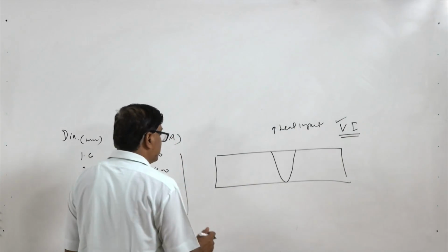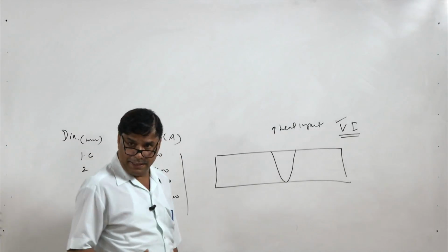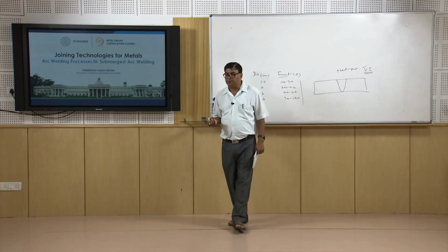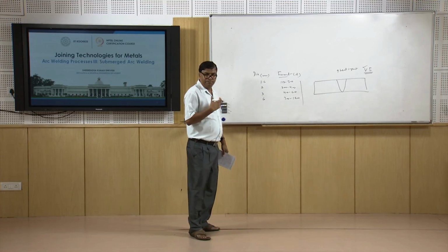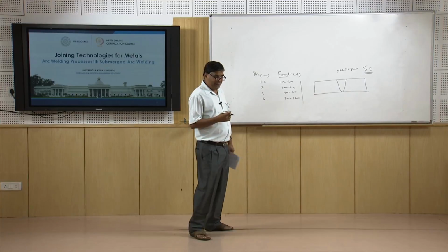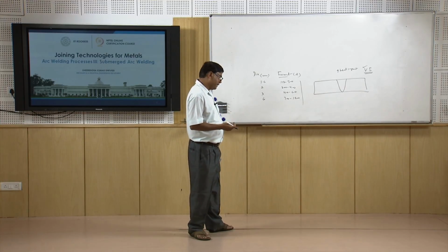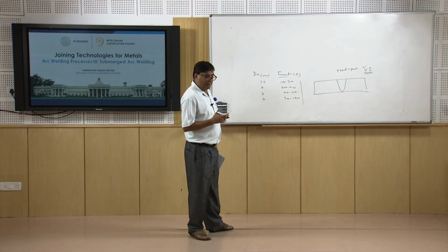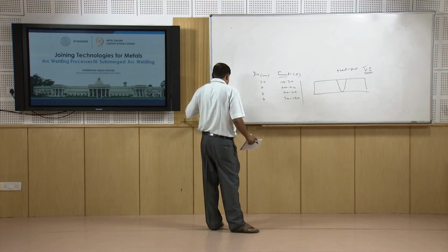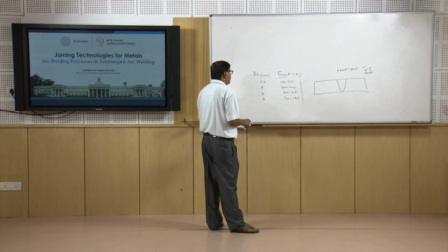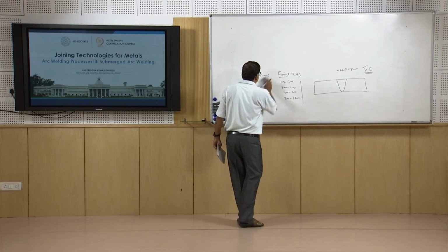Large diameter electrodes can handle the heavier current, otherwise excessive I squared R heating can damage the electrode, which will soften it, and the loss of its stiffness and rigidity can create a lot of problems related to uncontrolled metal transfer and placement of the metal where it is not desired, etc. So, as far as the welding current is concerned, these are the things.